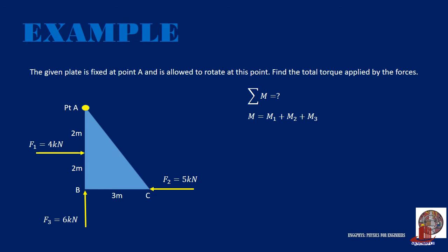While we expand, we can also consider the rotation altogether. So checking on force 1, which rotates counterclockwise, we can say that it is positive FL. The second force F2 moves clockwise, so it will be negative FL. The third force is a force through the point, so this will give a zero lever arm, making its FL value 0.